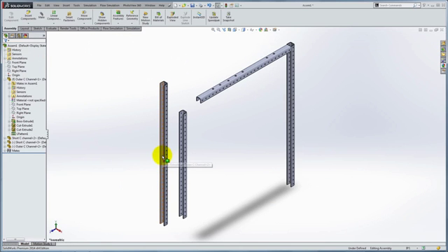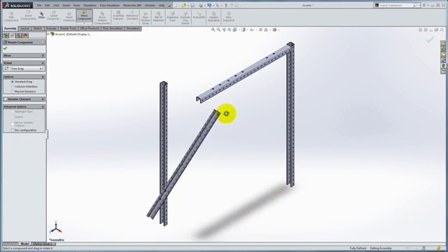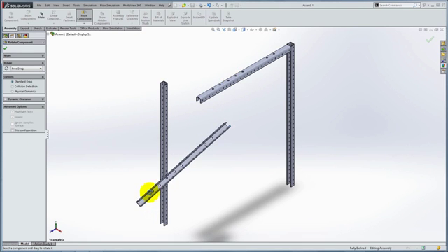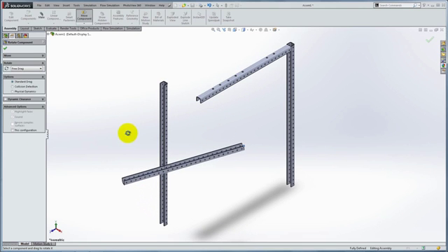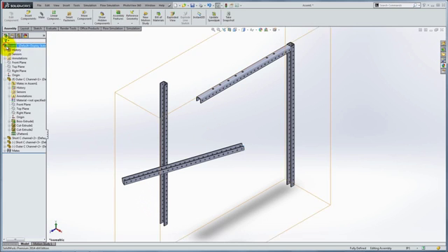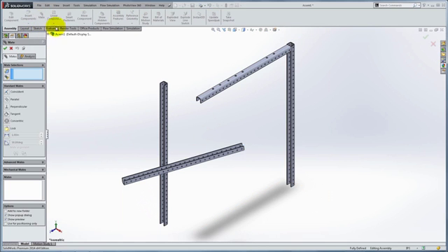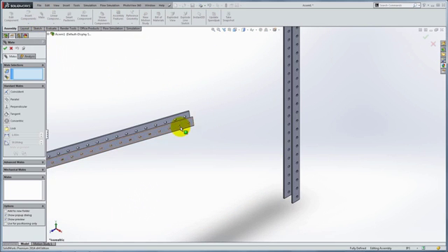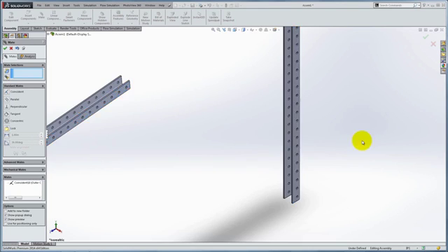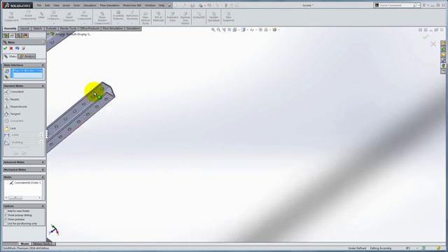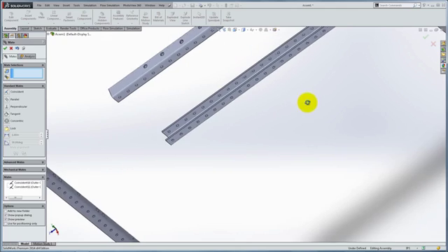Another useful tool for mating is the Rotate View tool. You can find it by going to Assembly, Move Component, and Rotate Component. Simply click and drag the components to rearrange them and make the mating process easier. Now go ahead and complete the rest of the robot base. Remember that there are countless ways to mate the parts and still obtain the same assembly.